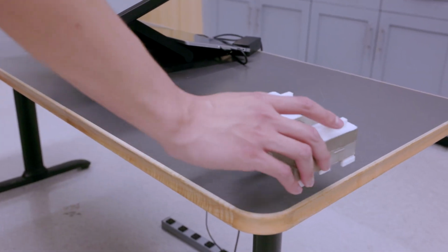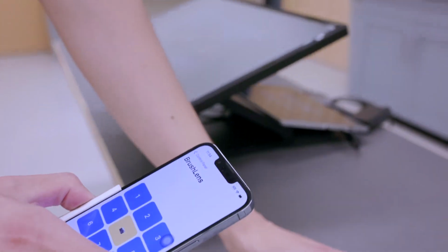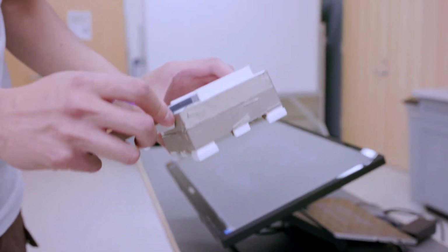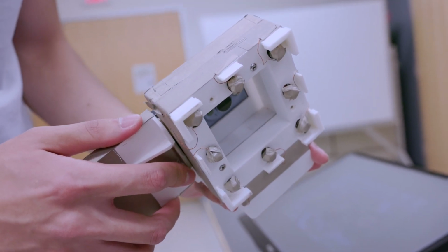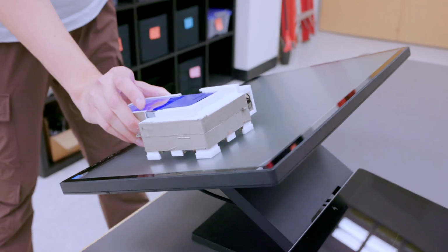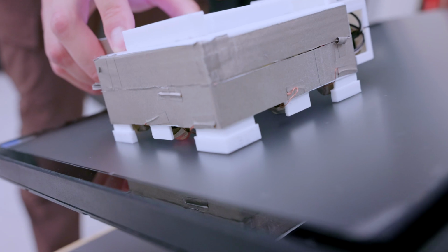BrushLens is a hardware device that is wirelessly connected to the user's smartphone. It can be attached to the smartphone as a phone case, and uses an array of solenoids covered with conductive fabric to actuate the screen. When activated, each solenoid can punch the screen, thereby simulating the touching gesture.